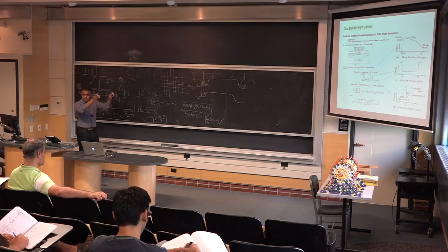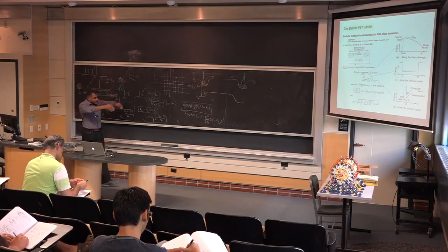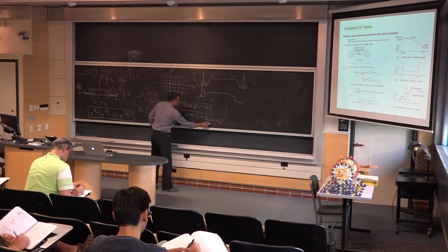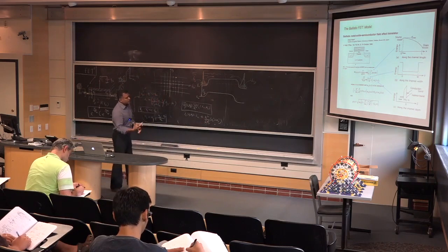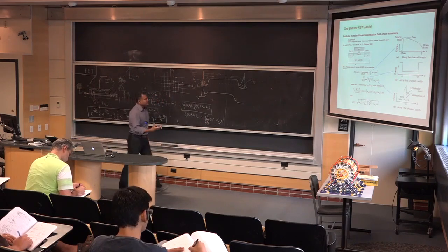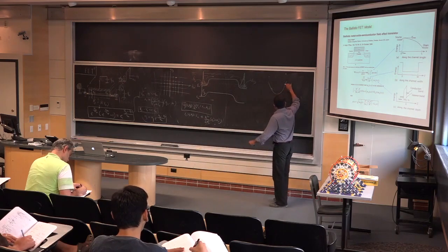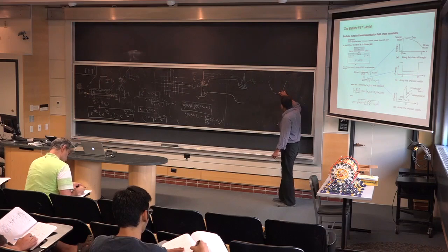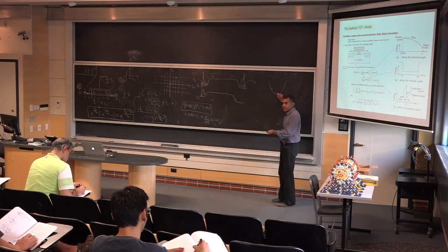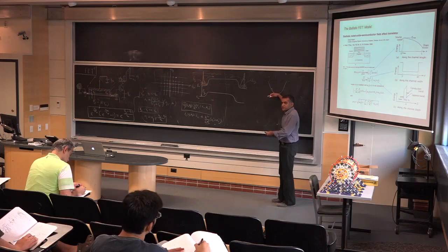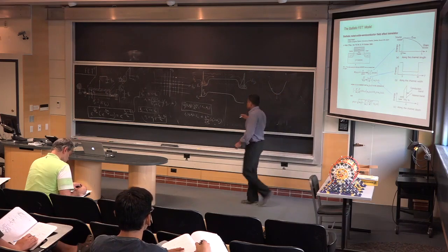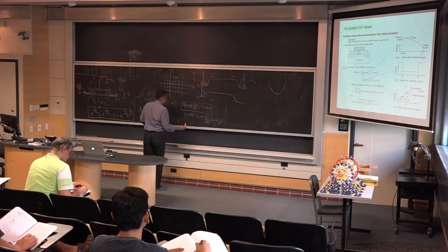The E-k diagram is parabolic. It's a reasonably good approximation as long as you're at the bottom of any band, because by definition, at the minimum of a function, no matter how complicated the function is, there is no linear term, there's only a parabolic one. Because the slope is 0. So at the minimum, this is always a decent approximation.